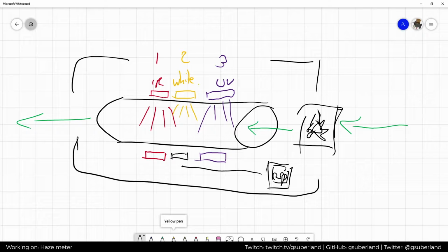So that will then connect to these, and obviously there will be some circuitry in there, which basically does all the analog gubbins that need doing for the photodiode side, the white LED detection stuff and the IR detection side. On the UV side, this is I2C, a tiny little package, 2 by 1.25 millimeters.